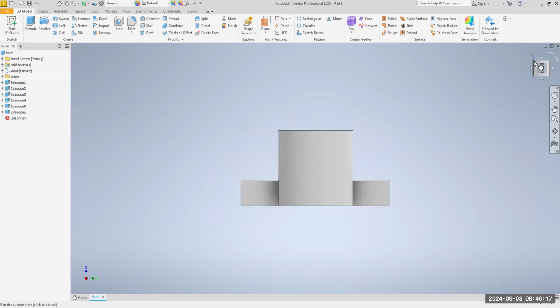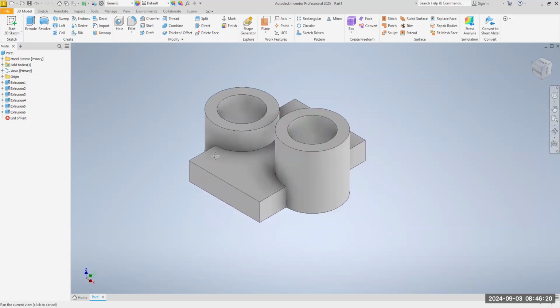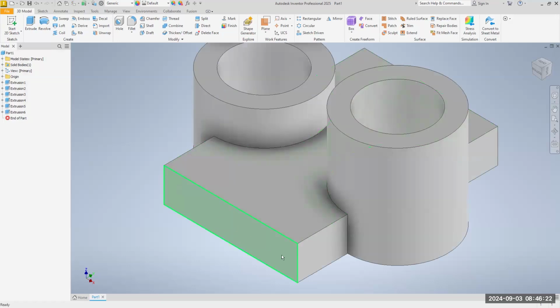Now what I want to do is this, is I want to round these corners here. See these corners here? I'm going to round these corners, okay? So here's what we're going to do. We're going to go to fillet. Fillet is a term that really means internal rounded corners, but I want to make external rounded corners. So you have to use fillet command for both internal corners and external. I want to round it off.